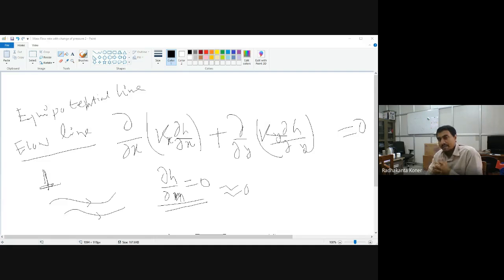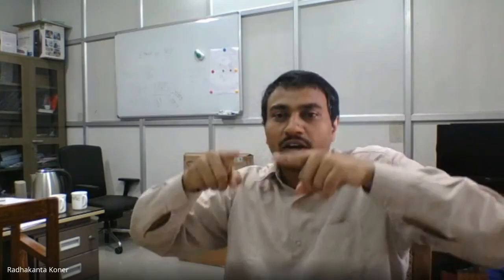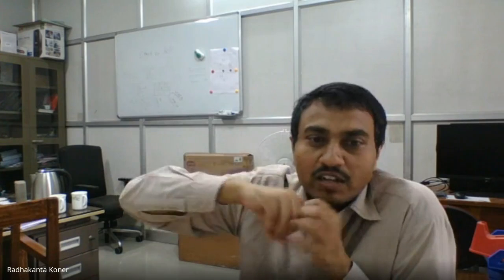And the area between the flow lines will form a curvilinear kind of square. So those squares we are going to measure, the dimensions of those squares. In those squares you can accommodate a circle, and from that you can determine the greatest diameter of the circle.